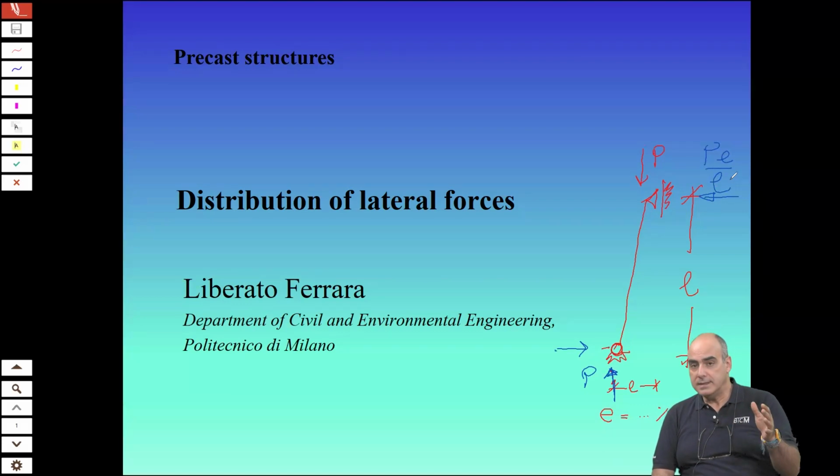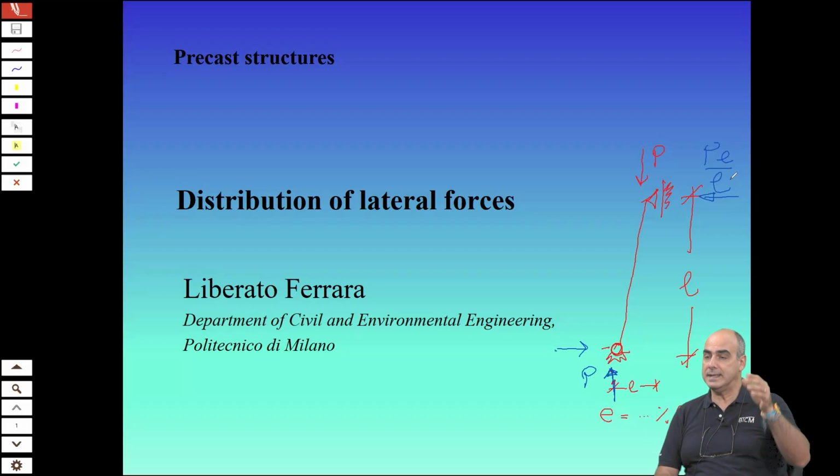So we always design precast structures to resist at least a lateral load equal to 2% of the weight.